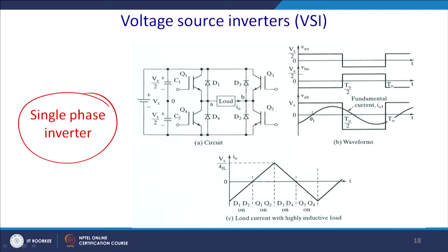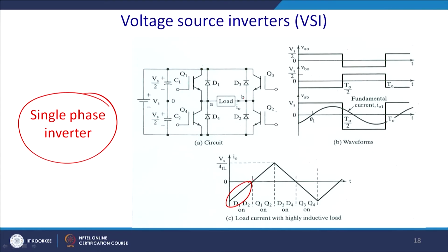And always remember, I said to you that try to decrease the value of the current, whether it is a positive cycle or negative cycle. Even if the ramp is positive, please see that the magnitude of the current is decreasing. Then always remember that the diodes are conducting. It sets the prelude to the switches' operation.